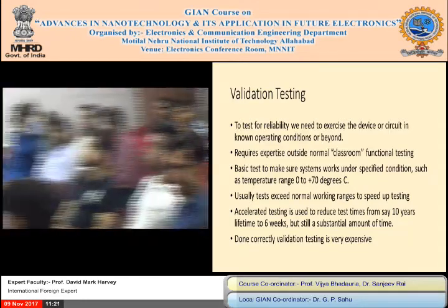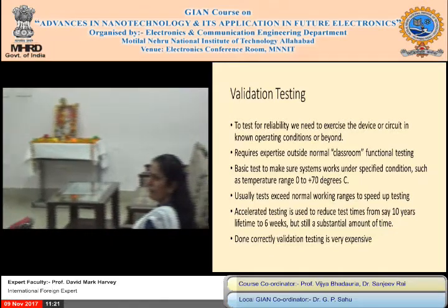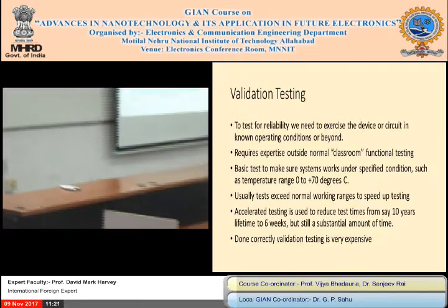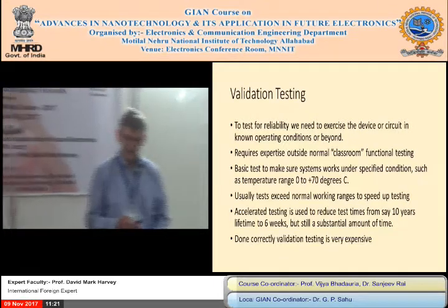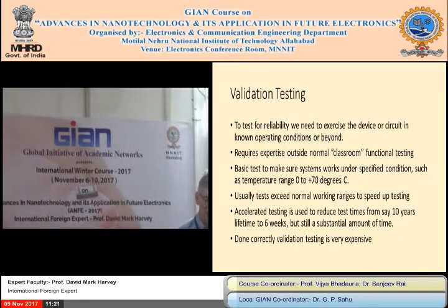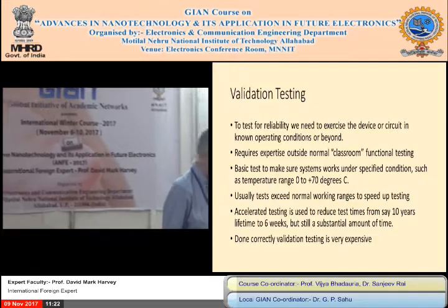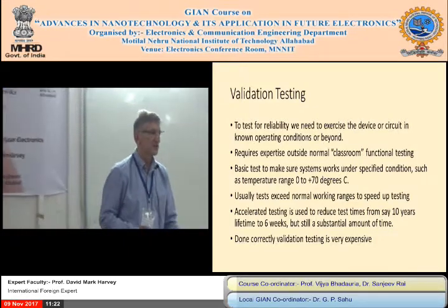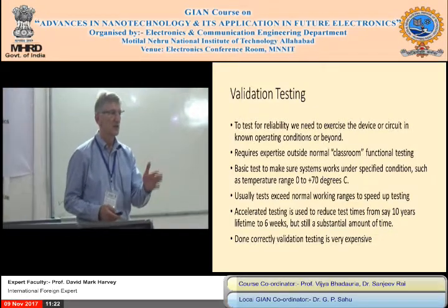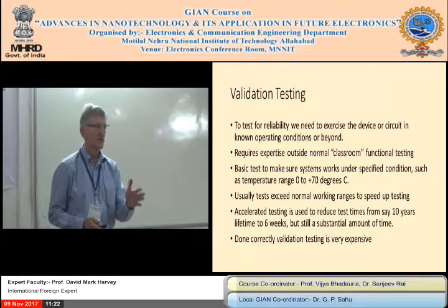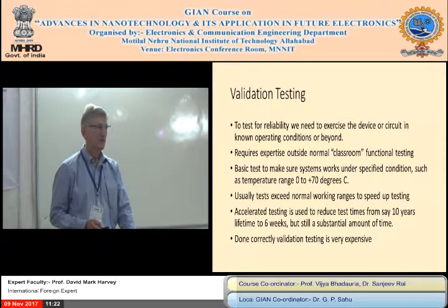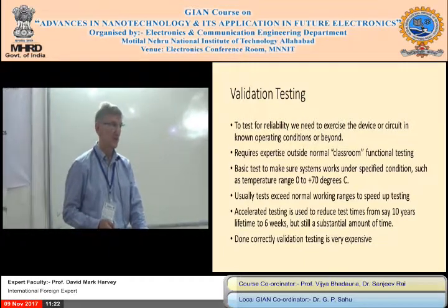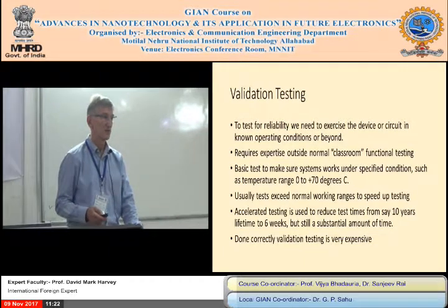So we were talking about this over the last few days. It's not just classroom testing. We've now got a whole temperature range to go. If we're not 0 to 70, we normally will extend it. And I don't know if I mentioned it, but a colleague of mine in industry said that testing a circuit board that's going into an automobile will cost you about £250,000, to make sure you're sure that it's going to work for 10 years.